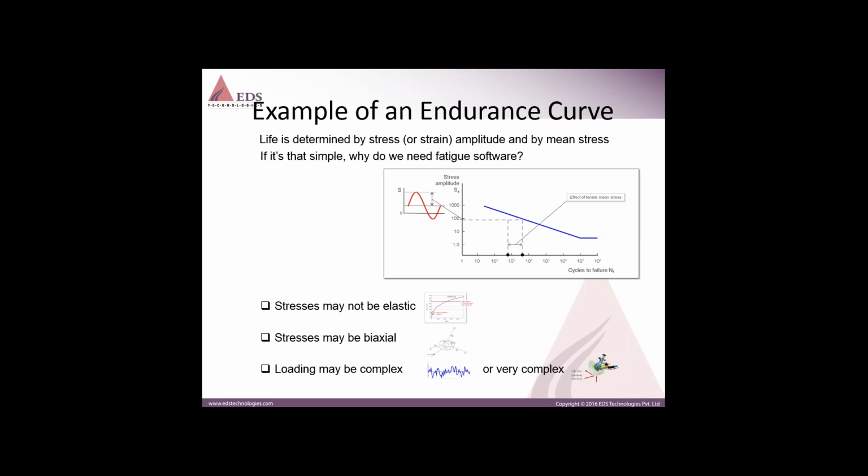Similarly, this SN curve is derived for uniaxial loading, whereas most of our applications are biaxial in nature. Similarly, the loading may be complex, or in some cases very complex, and the SN curve is not designed to handle this much